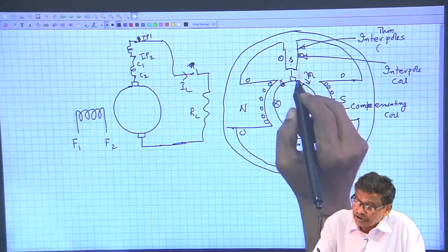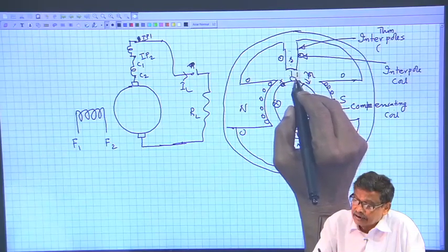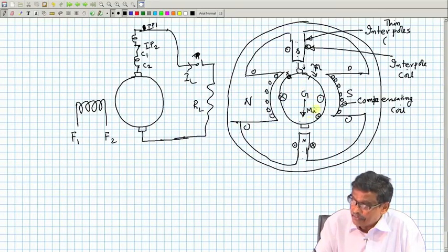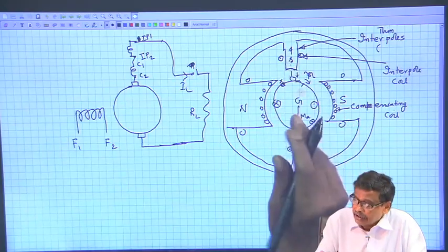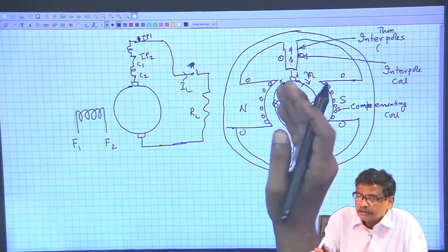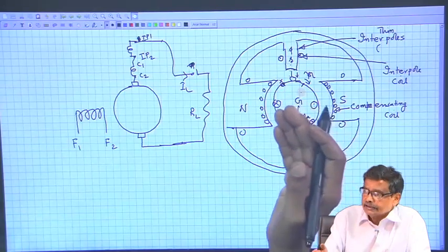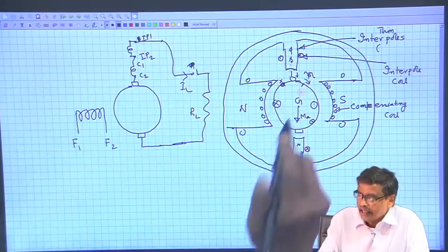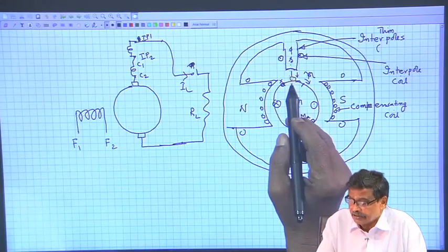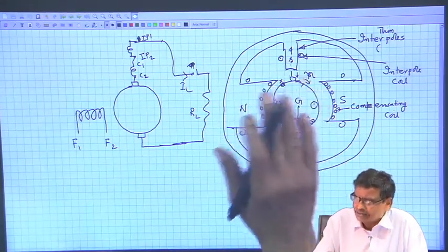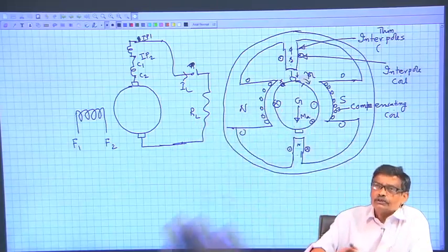The direction of the field was like this earlier under no load condition because of MA in this direction. What have I done? I have put another coil so that there will be a field there, these two may nullify, and therefore, quadrature B does not exist, no induced voltage, etc. And then the current here will be 0, then negative, some sort of smooth changeover takes place.